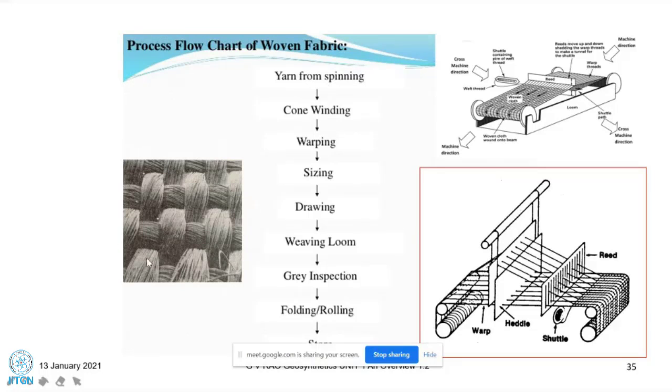This picture you have seen, the SEM view of a multi-filament woven geotextile. And we have also seen these pictures. So in this picture, what are we finding? We are finding that the yarns from the warp beam are coming out. They are not a muddled bunch of fibers. They are actually put in layers. You see one layer here and a layer here. There are thousands of these yarns. They are carefully wound in such a way that we can separate them into 2 or 3 or even sometimes 8 different kinds of systems.